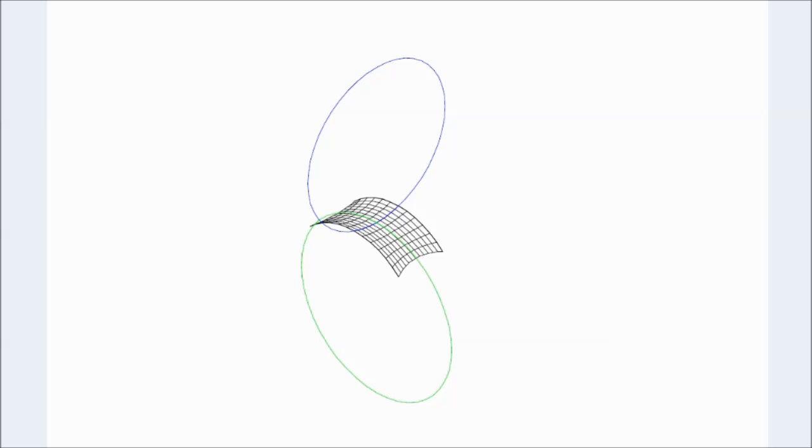At some load value, the structure will lose all hoop tension in one direction and will then behave, locally, as an inflated structure. This could be the point where large deflections start. The pre-stress value, which is determined by the amount of compensation applied to the fabric at an earlier stage, is the main value that determines how the structure reacts to loads. A high pre-stress results in a stiff structure that will resist applied loads with low deflections, but will need a strong material and supporting structure.